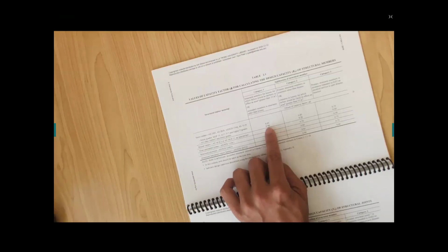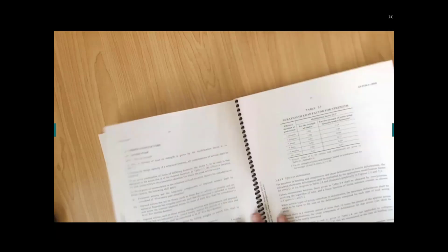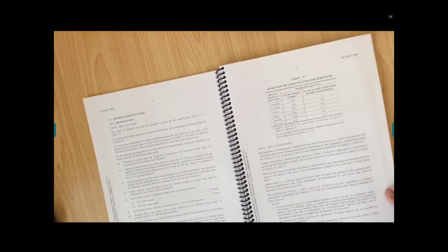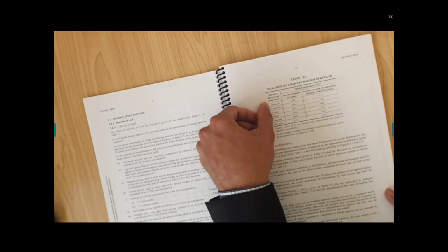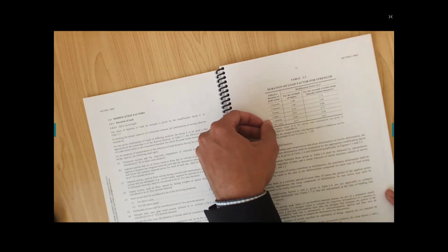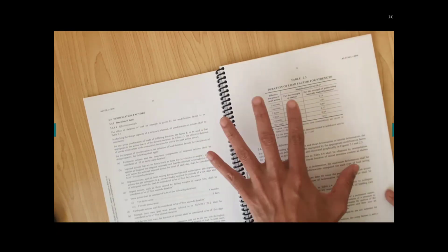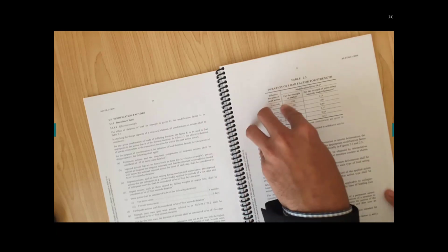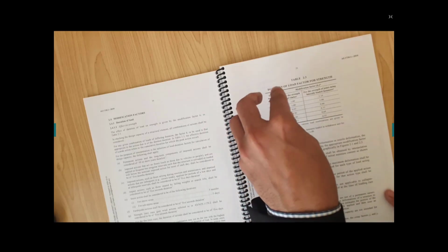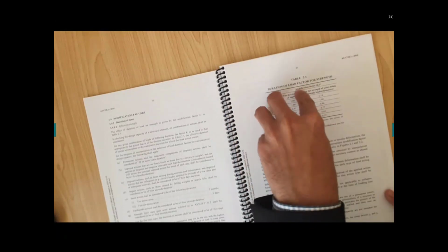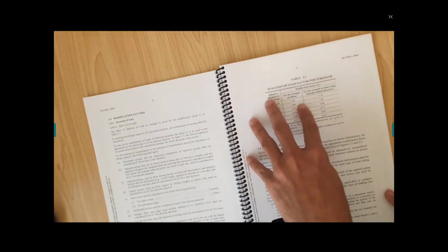K1 is, I think you remember, the duration of the load factors. Look, 5 seconds, 5 minutes, 5 hours, 5 days, 5 months, and 50 plus years. Students tell me, look, I'm designing it for 50 years, can I take this one? No. This is the probability of your members coming into the ultimate load situation in the given conditions.